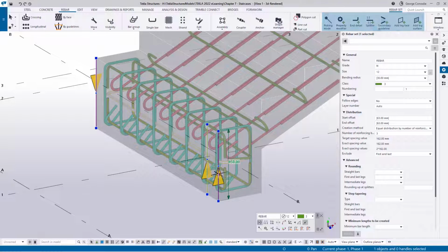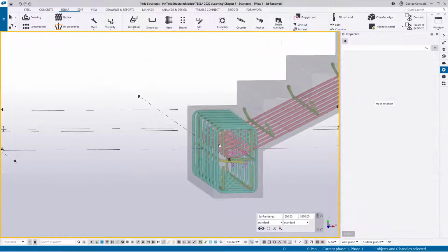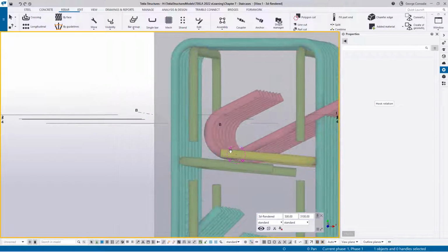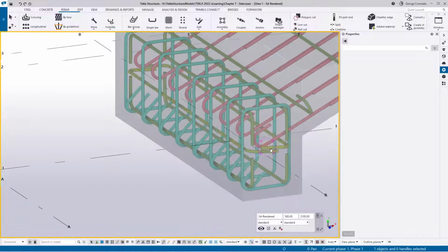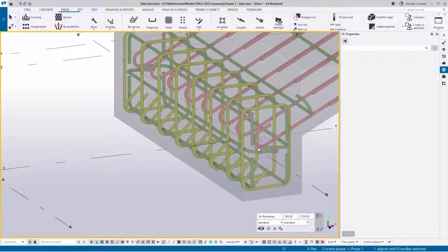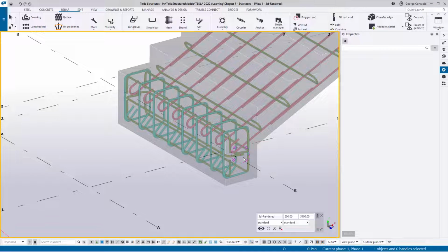Now, in this one, we go the opposite. So in here, we go 5 for this side, and for that side, we go -5. So just by rotating those bars, you can see we've avoided the clashes in them, and that's what they'll do on site anyway, without having to stuff around with spacing, moving bars up and down, playing with numbers, and eventually it bites you. It just doesn't work that way.